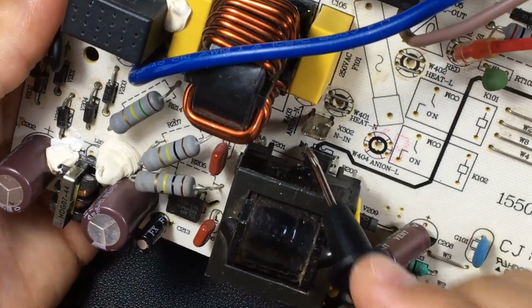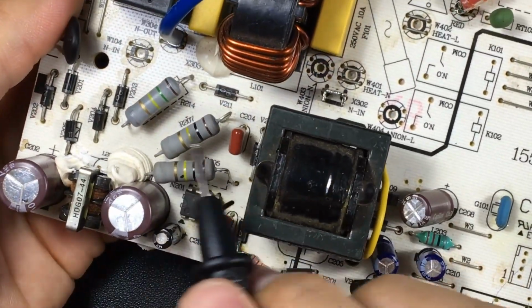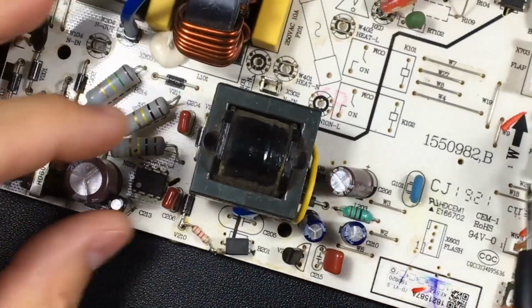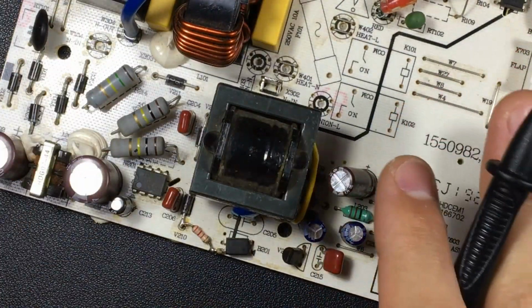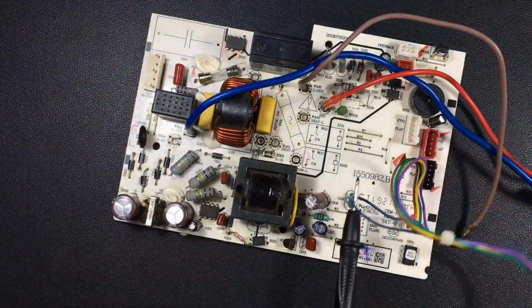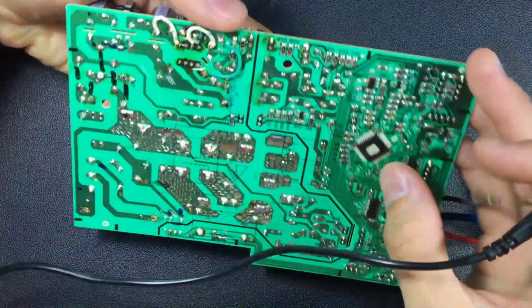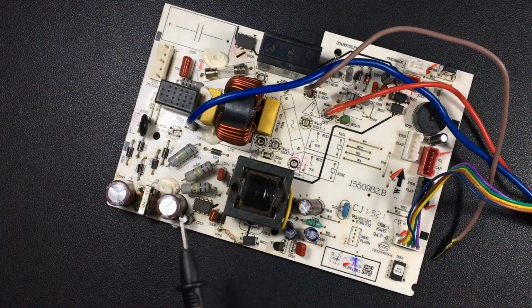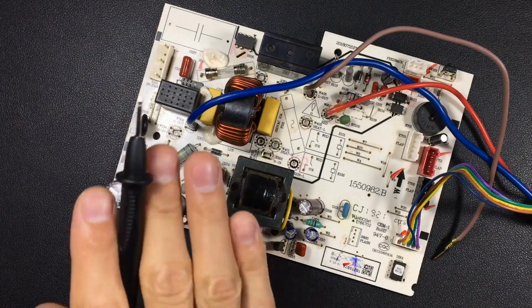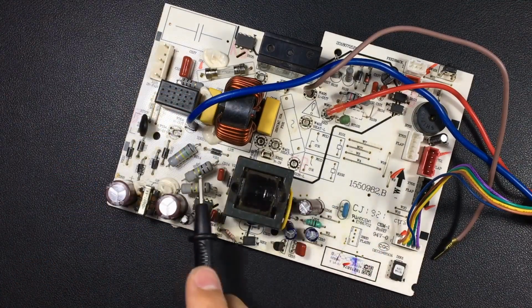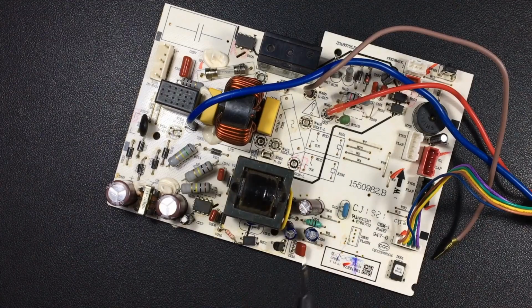In this case, the LED is placed on the side where the zero crossing is generated. That is, when we have to inform the consumption from the microprocessor area, the consumption is informed from the delicate area where the microprocessor is towards this side. And when we have to warn of the zero crossing from the side of the alternating voltage towards the microprocessor, the LED is placed precisely upside down.